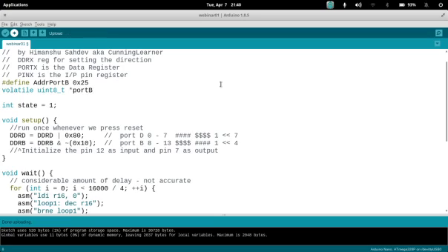Okay, and I think we need to typecast as well. Volatile uint8_t pointer. So what we are doing here is the address dereferencing method, and why are we using volatile? The volatile keyword tells my compiler that its services related to optimization are no longer required with this particular variable. So let us just create one.